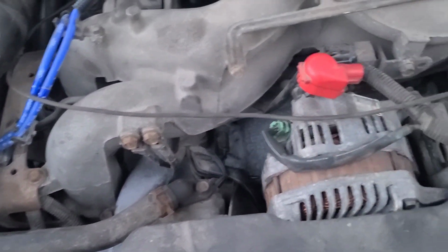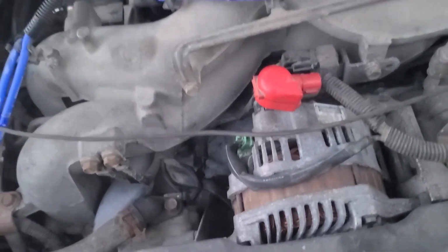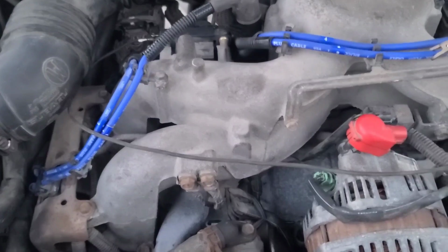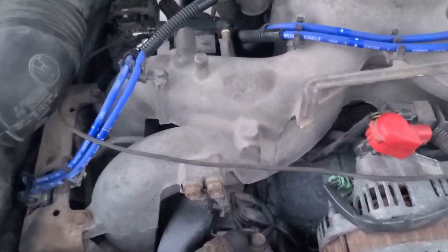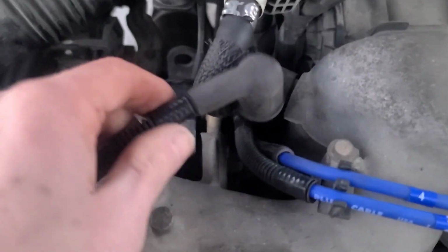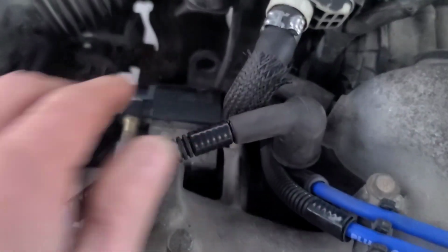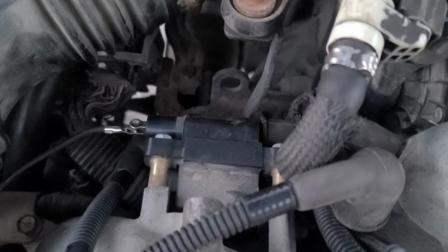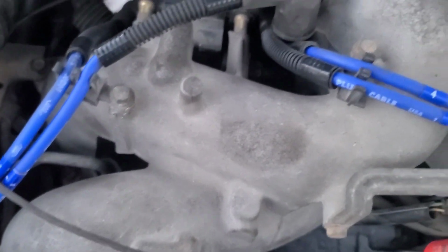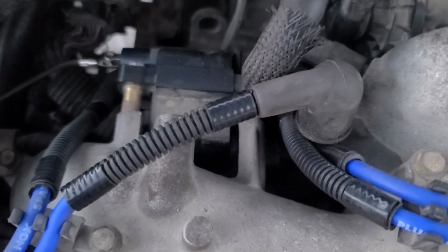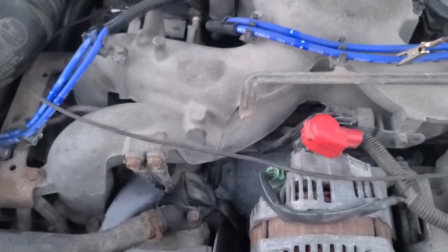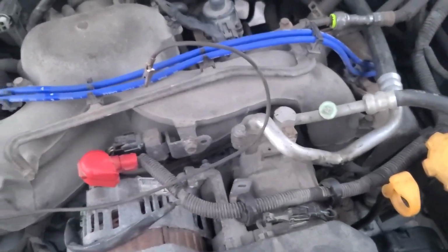Well, this is an interesting case. It appears that we have no spark, yet we had the ignition injector pulse according to the scan tool. It's not convenient to get to the control side of this coil. And it looks like the coil's been replaced. I know the plugs and plug wires have been replaced, but it looks almost like that coil might have been replaced. Yet there's no spark on that spark plug wire. The other spark plug wire is still attached to the engine, so it should have fired.